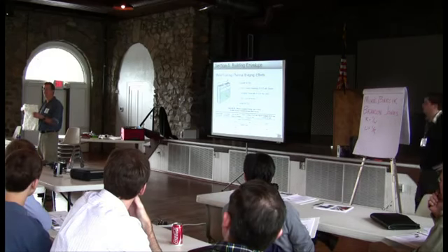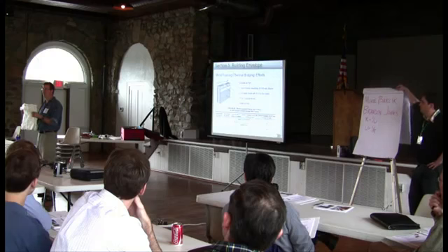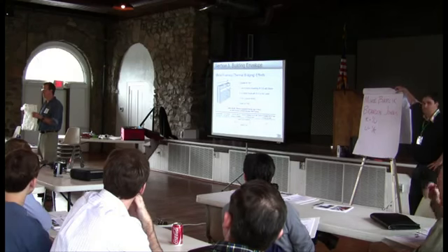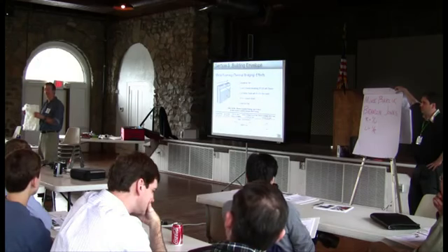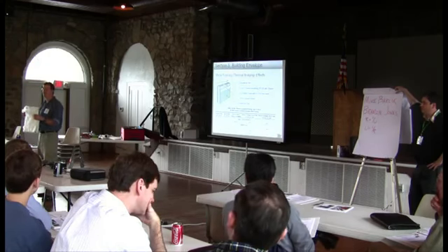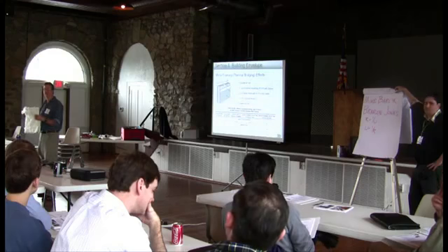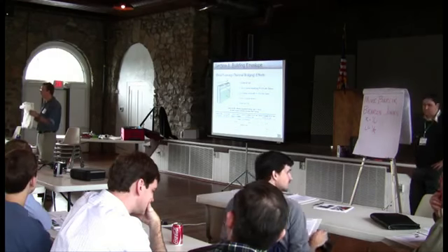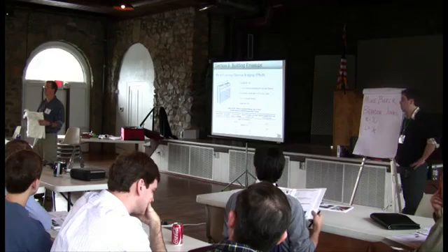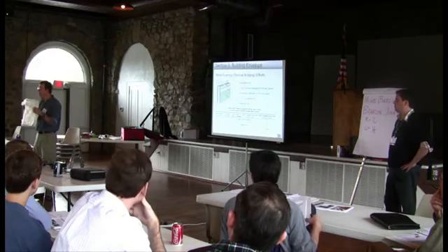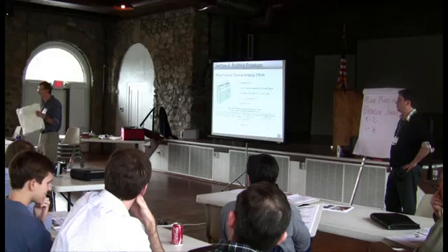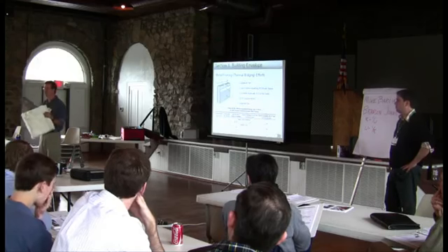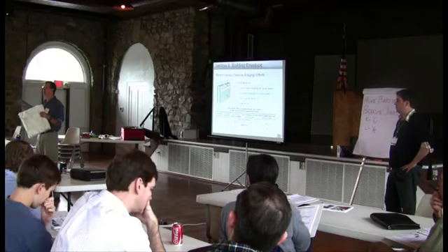No one raised their hand. Raise your hand if you think it's better than R9. R8. Actually, it ends up as R6, believe it or not. Isn't it amazing? It's an R13 bat, but it's performing as an R6 because most of the cavity is truly an R13, but what is the R value of the steel stud? We like to say we'll round it up to 0, right?